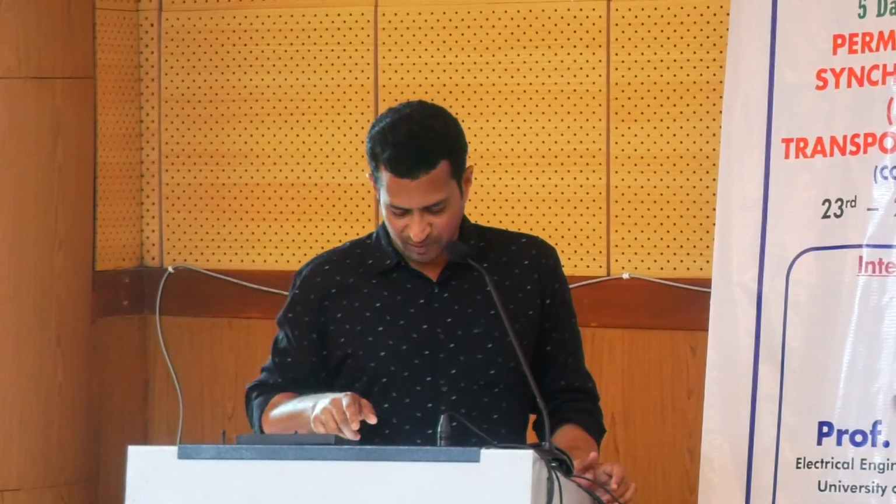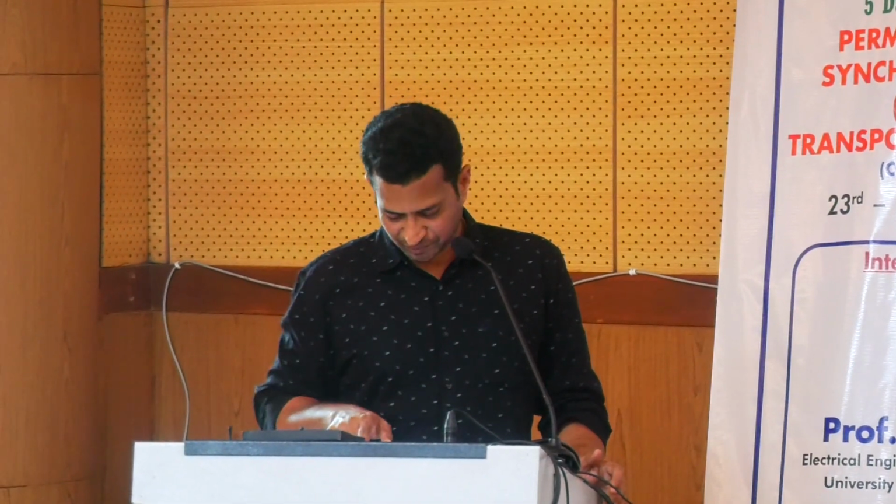Next we will discuss the fault tolerant operation of the converters, and also the modular multi-level converters for high power applications, especially high power drives aimed at applications like ship propulsion units. Also we'll discuss the reduced switch count multi-level inverters and their PWM methods.